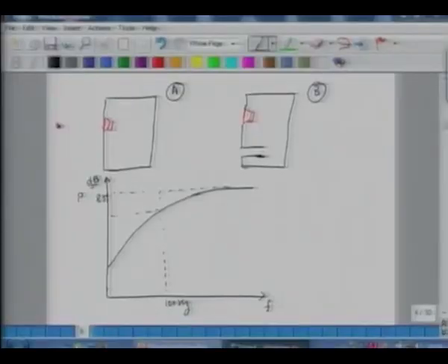So to solve this problem, what people do is they introduce a Helmholtz resonator in it, and it's a very inexpensive solution. They just introduce a tube in it. So you have a volume here and you have a tube, a port. So you have a spring mass system, and because of the resonance, they tune the length of the port and volume in such a way that the resonance is below some number. Let's say if I want to improve performance at 100 hertz or 80 hertz, then I tune this in such a way that my resonance frequency is at around 80 hertz